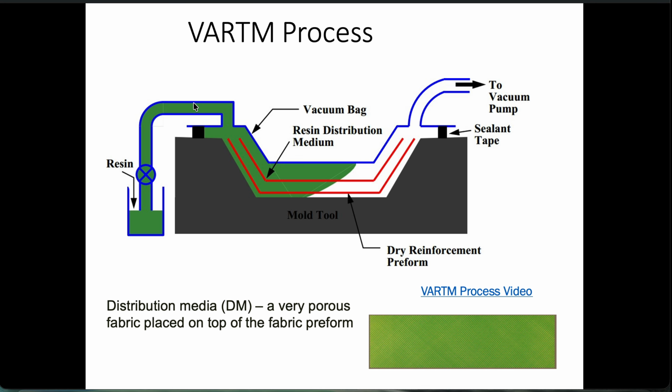You are going to suck air through your panel and out. This way, you make sure that there are no air pockets left in your composite panel. One thing you need to make sure of for this specific process is that your seal is perfect, so you can remove all of the air bubbles and air pockets from your system.